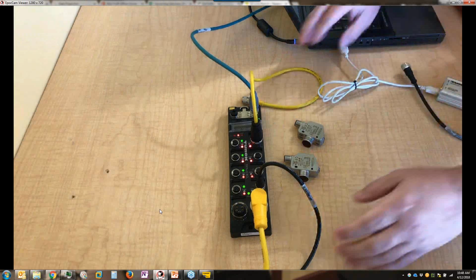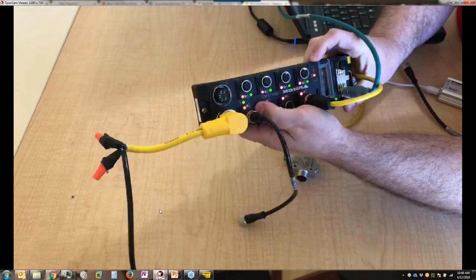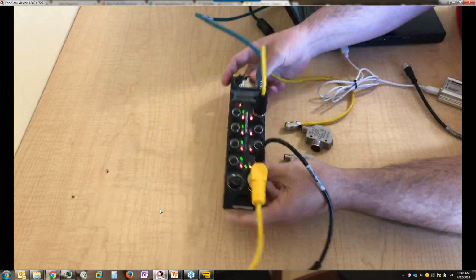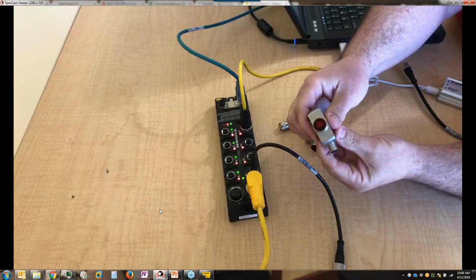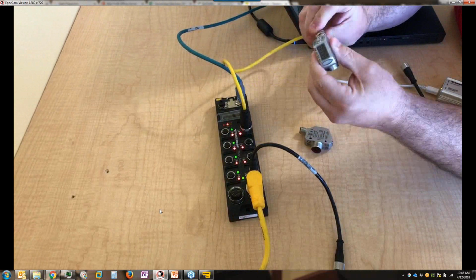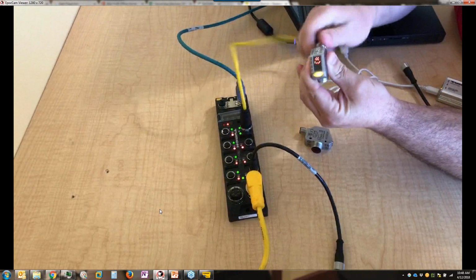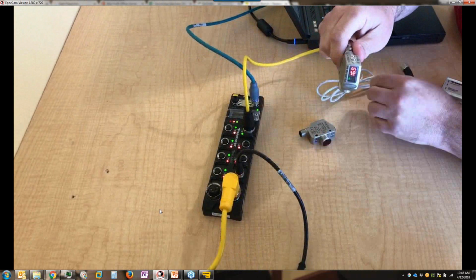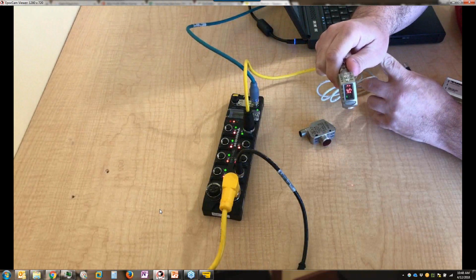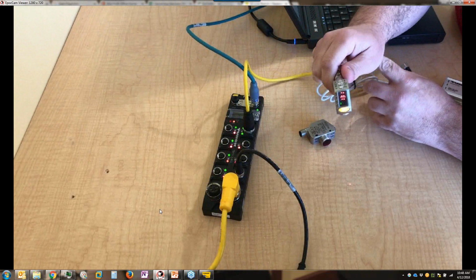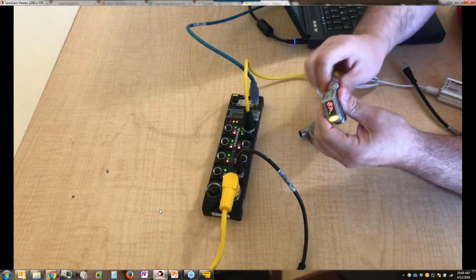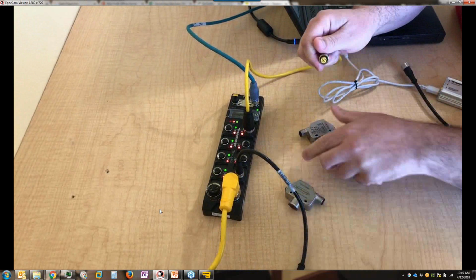Going back to my camera, I've got my cables plugged in to port number 1. That's easy to see. And port number 4 down here as well. So I'm going to take the Q4X that's not labeled. I'm going to plug it into port 4 and get power. There we go. And this is at the factory default state. So for a 300 millimeter sensor, the trigger point should be 150 millimeters, and it is. And we can see the light on the front of the sensor change state. Okay. I want to plug in the other sensor that's labeled BH.